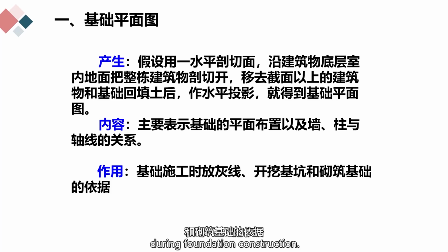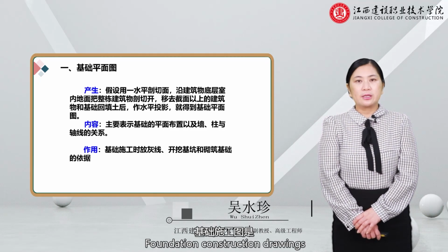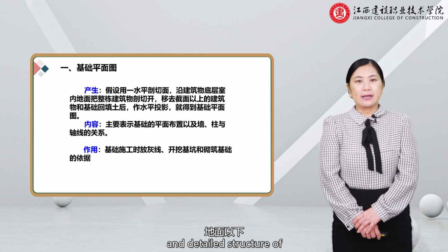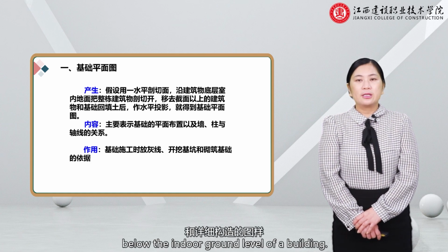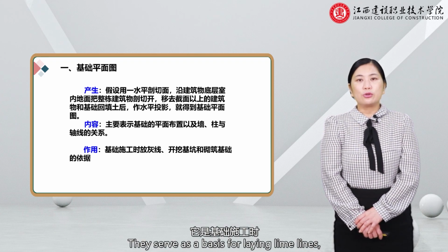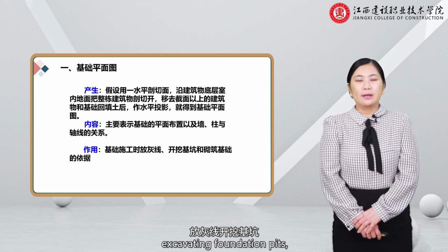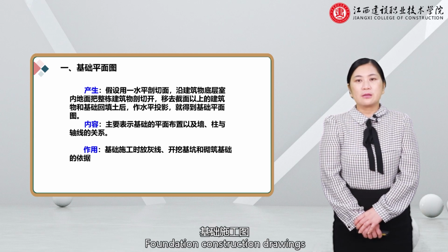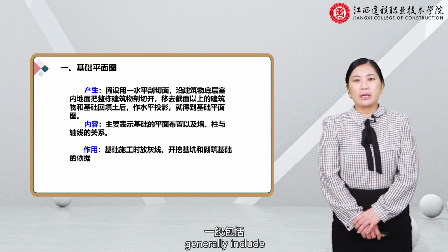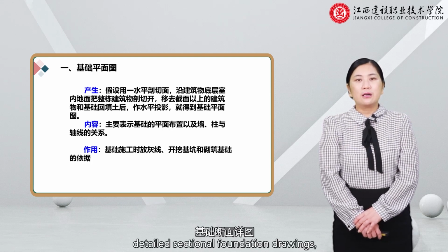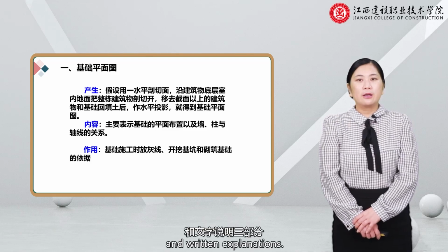During foundation construction, foundation construction drawings represent the planar layout and detailed structure of the foundation part below the indoor ground level of a building. They serve as a basis for laying lime lines, excavating foundation pits, and constructing foundations during foundation construction. Foundation construction drawings generally include foundation plans, detailed foundation drawings, detailed sectional foundation drawings, and written explanations.